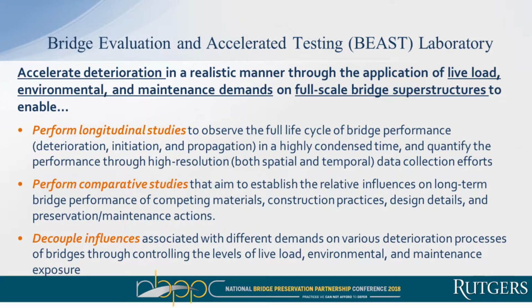And so what we did, in partnership with New Jersey DOT, is develop an accelerated testing facility. The goal was to accelerate deterioration of bridges in some sort of realistic manner through applying live loads, environmental, and maintenance demands to full-scale superstructures. Those were the requirements. Through that, we can perform what I'll call longitudinal studies, which means we can build a structure in there and track its performance with time to try to update deterioration curves, right?